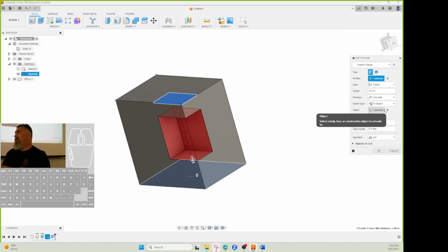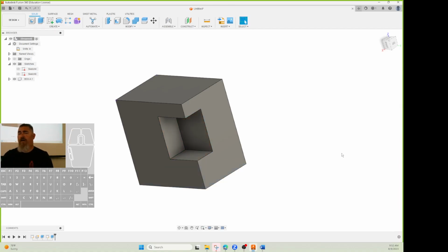Yeah. So now that you have that cut in that square, is there a way to mirror that cut into an object really quickly? Yes, of course. We're not going to do that today, though. If you want to figure it out, figure it out. That's why I said we draw a half, we flip it over to the other half, right? So we'll do that. But if you want to try, go ahead and figure it out. But for right now, I want you to get comfortable using the extrude command. Okay? Any questions?